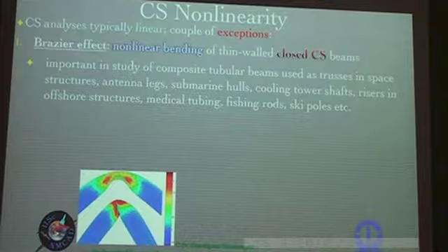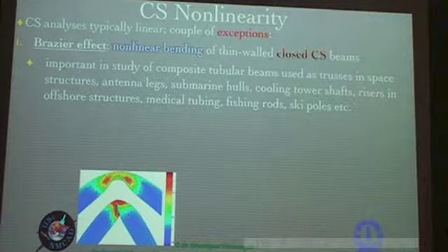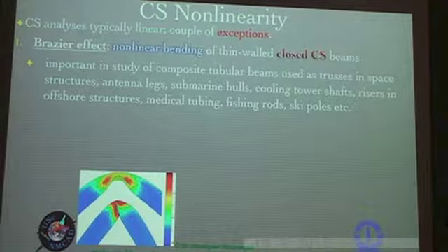So in other words, you can consider the region between two transverse stiffeners as basically the beam. What it makes is a shorter beam, a stubbier beam basically, so making the transverse shear effects probably more important.